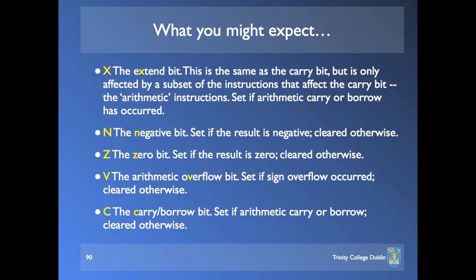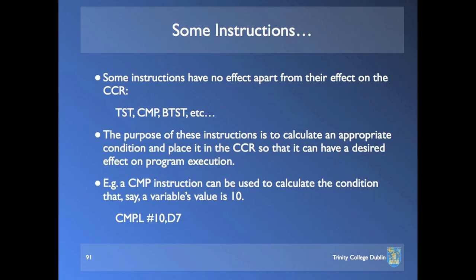Not quite. You really do have to study the instruction set summary very carefully. So, for instance, I think if you move something into the data register, then the condition code register is set, as you're suggesting. If you move something into an address register, I'm pretty sure it's not. You need to look at the instruction set summary very carefully. Okay? And it has to be part of your consideration. Which instruction am I going to use? Where am I going to put the data? And so on.